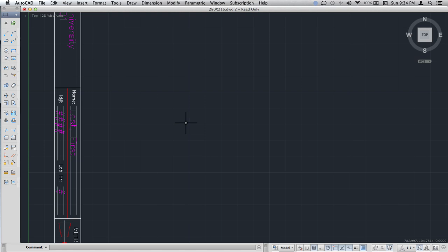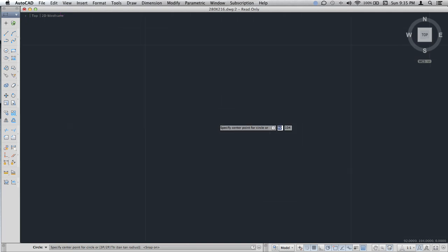So let's go ahead and draw some circles here. Circle. Okay, and you can toggle the snap by simply hitting F8, and you can see here, maybe I'll zoom in, see how it's snapping to different points here. I'm sorry, not F8, F9, okay?